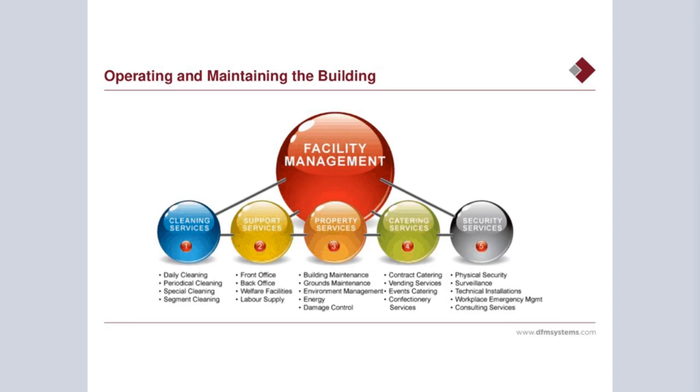Anyone working on the building doing modifications or extensions must also be able to access the safety file to alert themselves to any inherent risks associated with their intended work. And also, importantly, the safety file should contain any information needed in relation to future demolition, any risks associated with future demolition of the building.